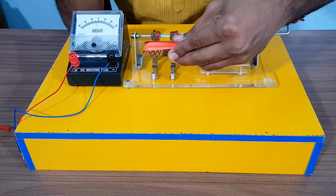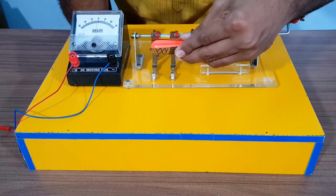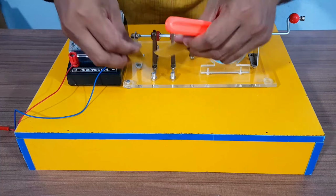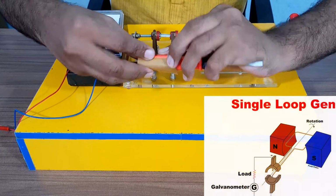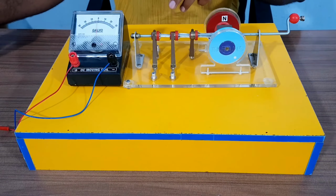This is not a split ring, this is a slip ring, which we use in an AC generator. In a DC generator, it's a split ring, meaning there are two plates attached in this way. So in half a turn, they are disconnected from both sides. Such a structure is here.